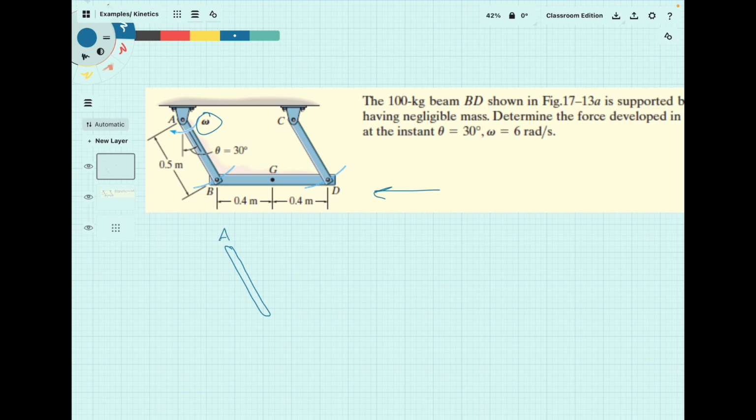It's just rotating about that, and as we've seen before, if you're rotating at a constant velocity, you can view your system as a normal tangential setup like this, where that is your normal tangential system. And then down here at B, we can solve for the accelerations there. Now, since omega is constant, alpha is 0 for bar AB at least.